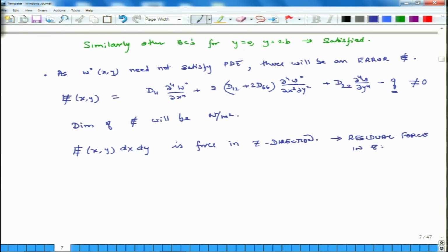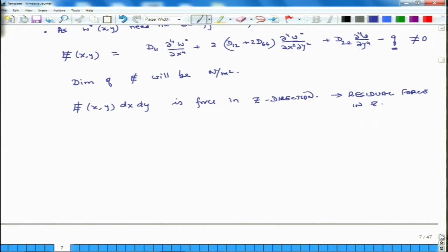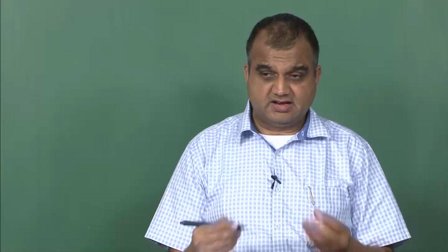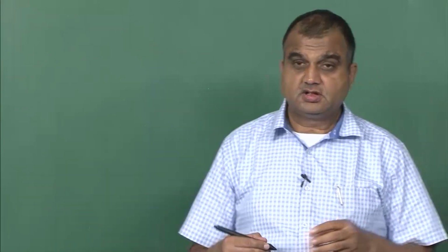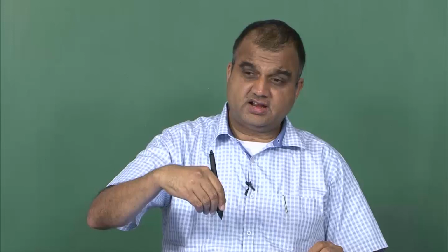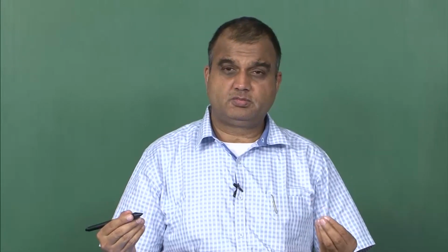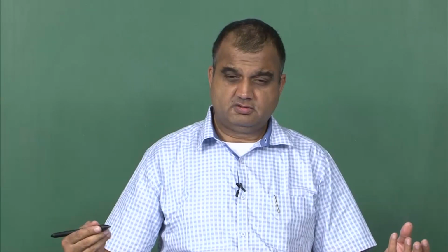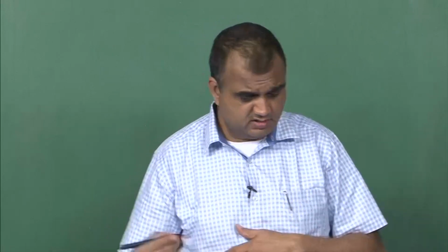In z direction, the residual force in z direction. Now, what we say is that if there is this residual force in the z direction, and if I multiply it by some virtual displacement, and I will explain what is a virtual displacement. So, if this is the residual force in z direction, and if there is some virtual displacement in z direction, then what is the product of virtual displacement and this error force? It will be work, right.